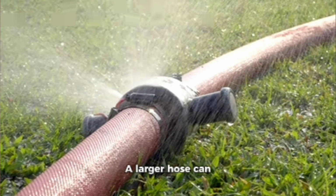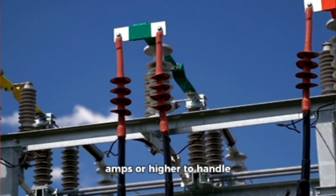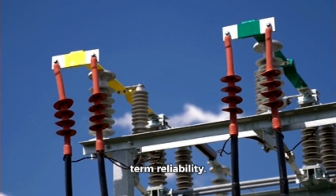Now, we need to choose an incoming isolator and an ELCB that can handle this load. Since the current is around 82 amps, we should select components rated higher to ensure safety and future flexibility. A good choice is an ELCB and isolator rated at 100 amps. By choosing an ELCB rated at 100 amps, we're not only covering the current needs but also allowing for future expansion without compromising safety. The same goes for the incoming isolator, which should be rated at 100 amps or higher to handle the load and ensure long-term reliability.